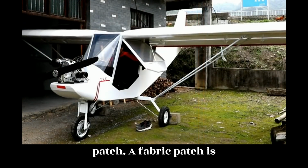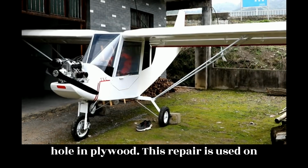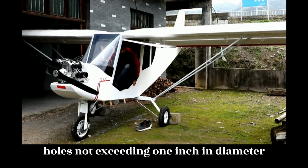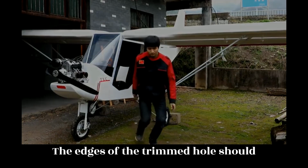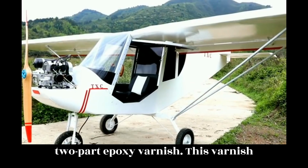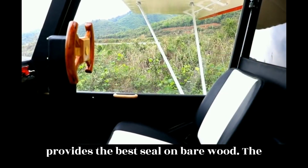Fabric patch. A fabric patch is the simplest method to repair a small hole in plywood. This repair is used on holes not exceeding 1 inch in diameter after being trimmed to a smooth outline. The edges of the trimmed hole should first be sealed, preferably with a 2-part epoxy varnish. This varnish requires a long cure time, but it provides the best seal on bare wood.